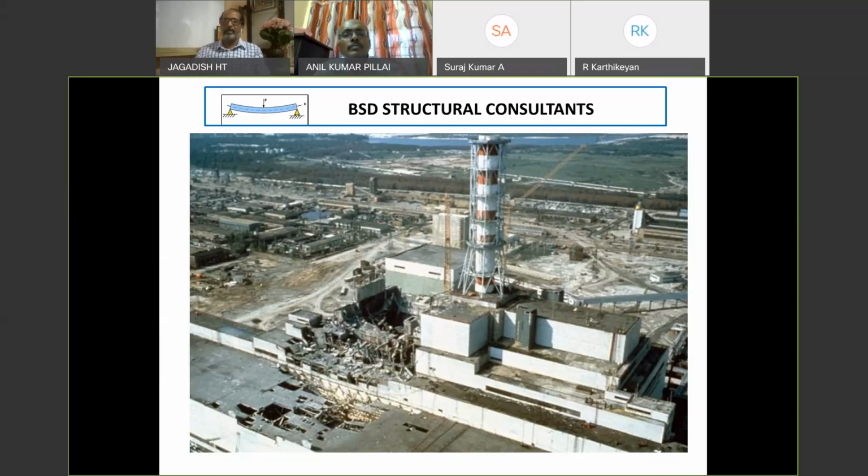Control room was aware that R&D is going on. So at one point of time, somewhere water leakage happened, not due to R&D, but due to some other reason. The coolant started leaking out, and the control room people didn't realize that this is actually happening not due to R&D. They thought because of R&D, some water is getting drained out. So they overruled the indication and they continued operating the reactor. At one point of time, the leakage happened so high that the reactor temperature went on rising very high.